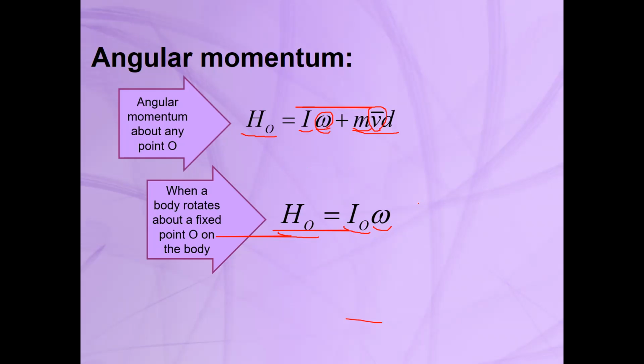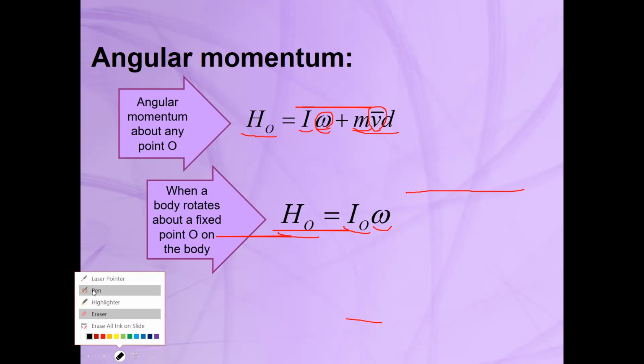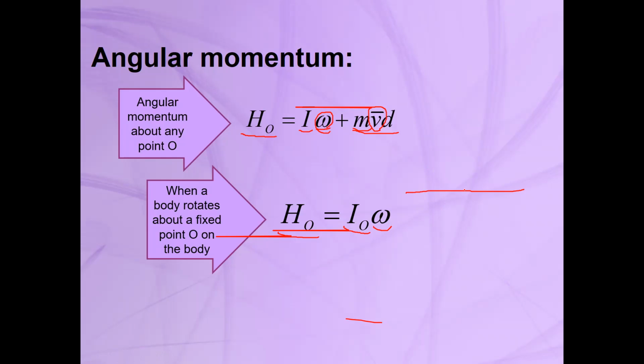A simple example for this case that sometimes we use is again the rotation without slipping. When we have a wheel on a surface and it's rotating without slipping, exactly at this contact point, we can assume that this wheel is rotating with a pure rotational motion.